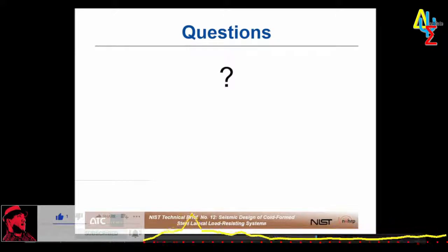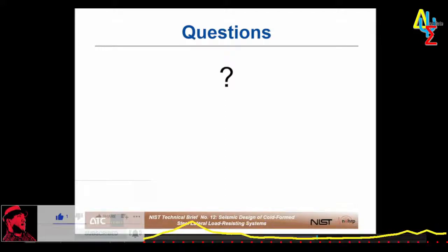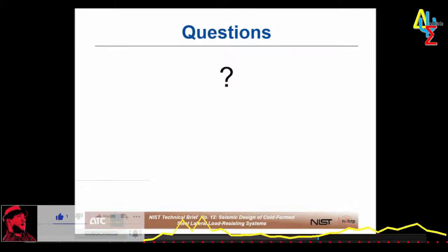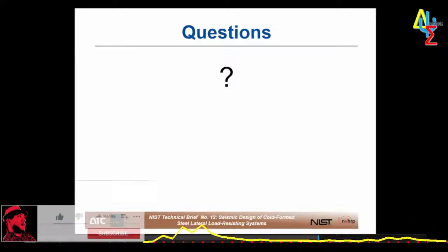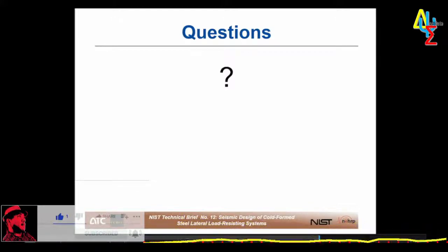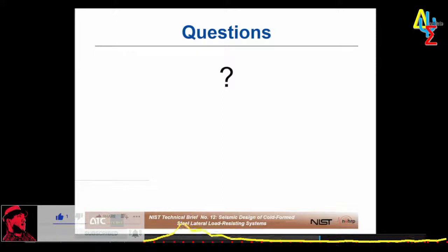I think there's a number of things you have to think about if you're contemplating using gypsum board as part of your primary lateral force resisting system or seismic force resisting system. Damage is one of them. For example, somebody decides to do a remodel and pulls the gypsum board off. You've kind of lost your lateral system. Also, in the event of water damage, and water damage can be from a number of sources, right? It could be from a flood or a leak in your plumbing system, or it could be because there's a fire, and the firemen come in with their hoses and start squirting down your shear walls. So yeah, there are some specific limitations, but in addition to those limitations, I think a lot of practical consideration needs to be made with regard to when a gypsum shear wall would be appropriate.